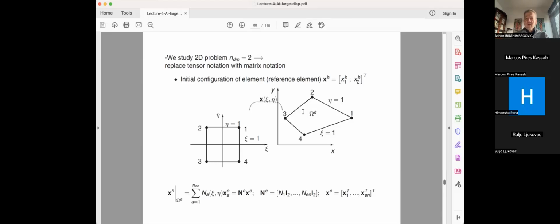Typically, the way you know is that when you compute the Jacobian, the determinant of the Jacobian matrix takes a negative value. Then you know that something went wrong. So it's advisable in this computation to always have a check of the Jacobian value, making sure it is positive, so that you know the transformation is still valid and you have no problems related to this type of error.